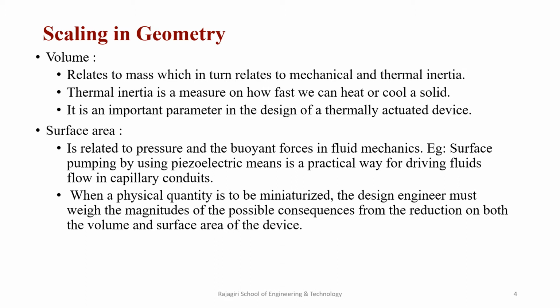On the other hand, surface properties like surface area are related to pressure and buoyant forces in fluid mechanics. It is also related to the heat dissipation or heat absorption by a solid. For example, surface pumping by using piezoelectric means is a practical way of driving fluid flow in capillary conduits. So when a physical quantity is to be miniaturized, the design engineer must take into consideration the magnitudes of the possible consequences from the reduction on both volume and surface area of the device.